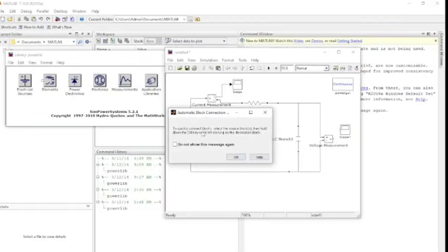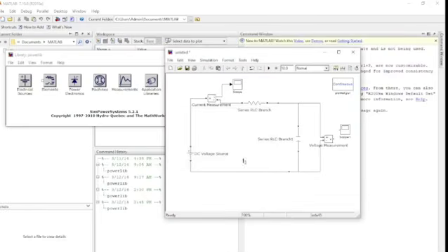What this says is that if you want to quickly connect the blocks, you can select the source block and then hold the control key while clicking the destination block, so connections can be done directly. So you select this particular block, then hold the control key and click the destination block, which will make the connection automatically. This is what it says. Either way, you have to do all these connections.